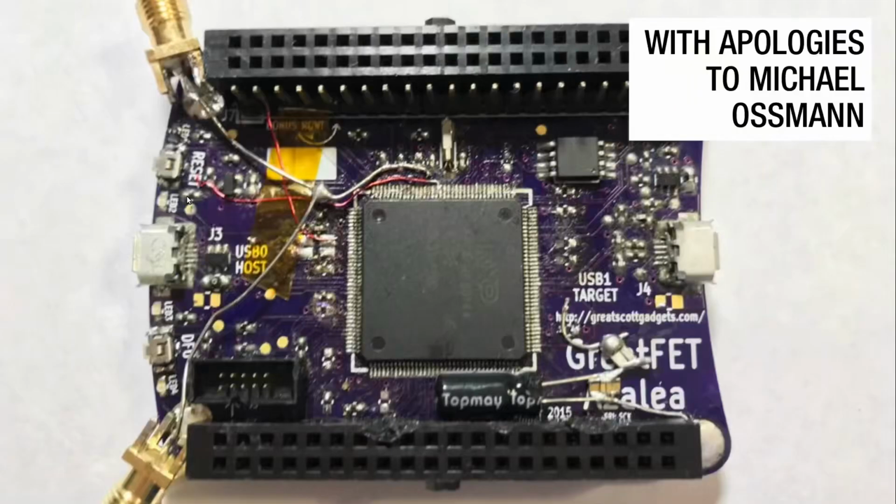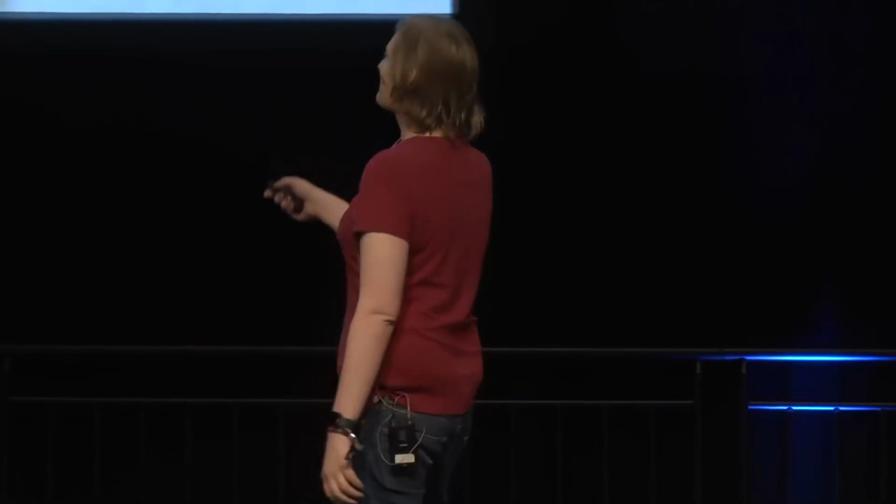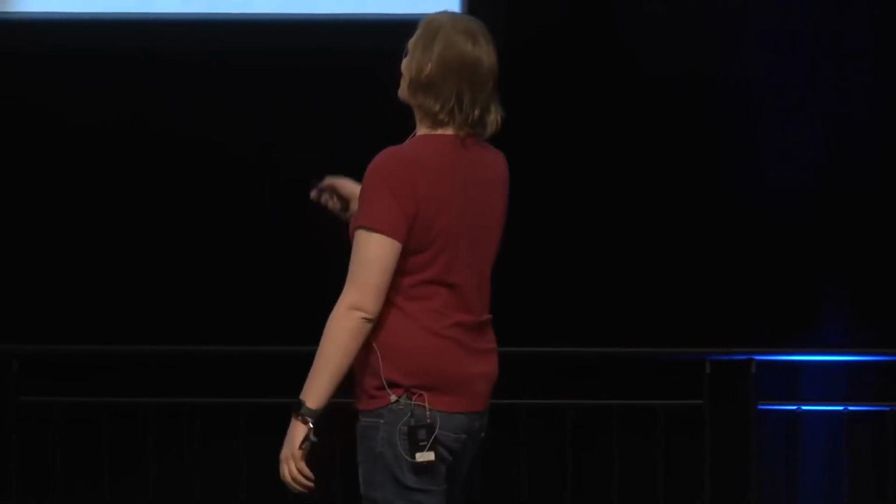So naturally, we're not content with just reproducing other people's work. We wanted to try doing some cool things of our own. So at some point, we had to turn against our own creation, right? And so here is a GreatFET that has been actually sloppily modified. I promised the board had all the flux on it before we made modifications. But I've yanked every one of the decoupling capacitors rather roughly off this device, to make it easier to start depriving the device of power.